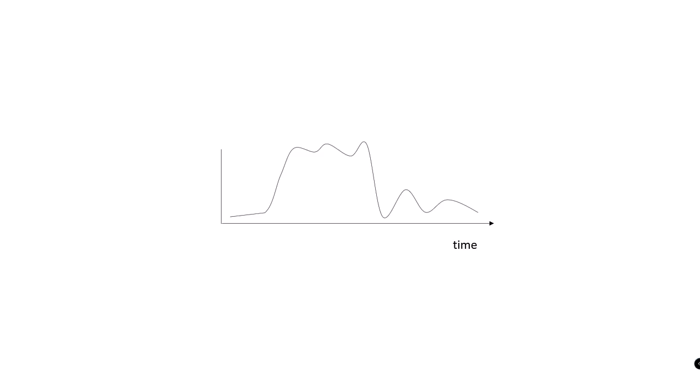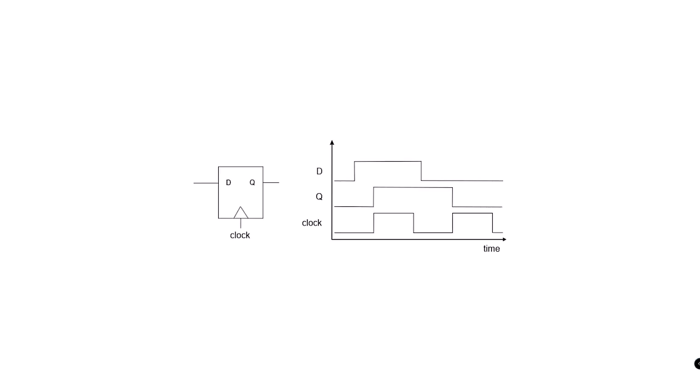The clock signal also needs to be free of noise. Variations in the clock signal might cause other circuits to see a spurious clock event. High-performance design requires us to carefully analyze the distribution of the clock signal to be sure it meets our requirements.